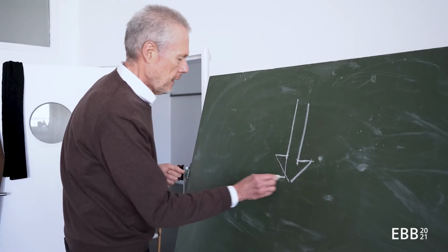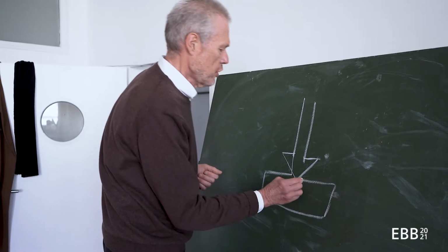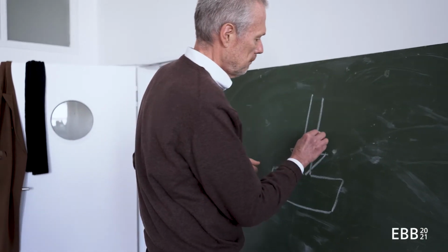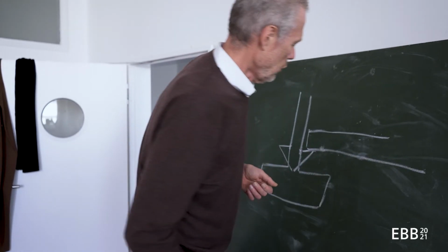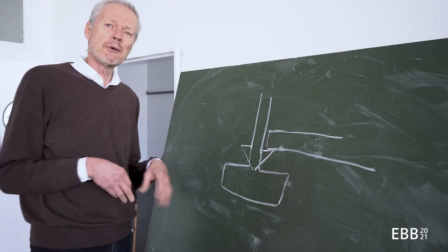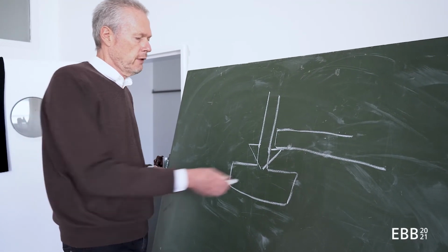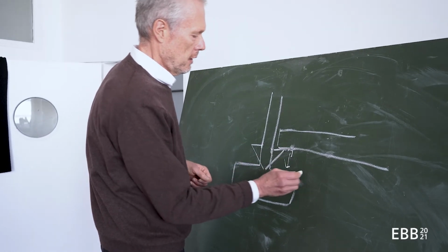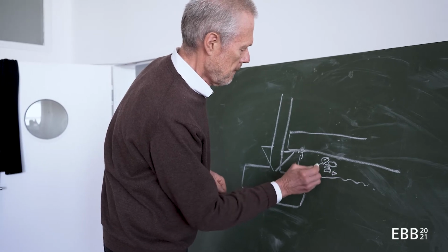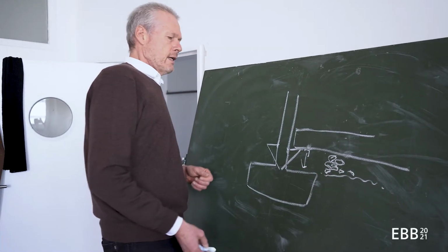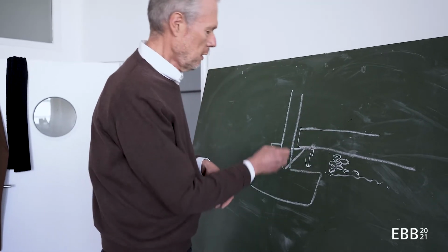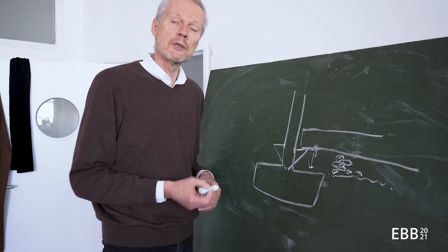So I have been introducing a foundation, and I also need a support for the bottom floor slab, which today very often rests directly on the ground. So if I distance this a little, I can introduce a layer of gravel here underneath, and I ensure that this horizontal slab rests on the gravel and not on the side of the foundation.